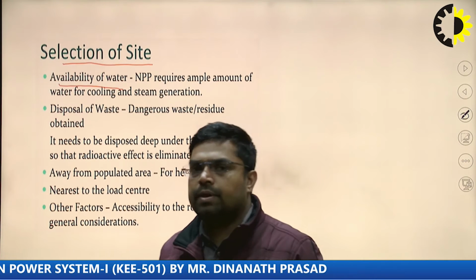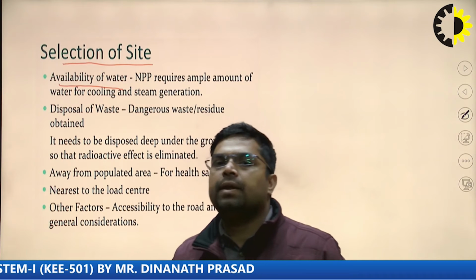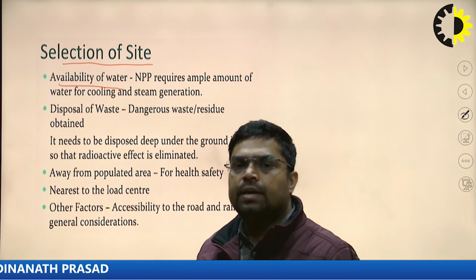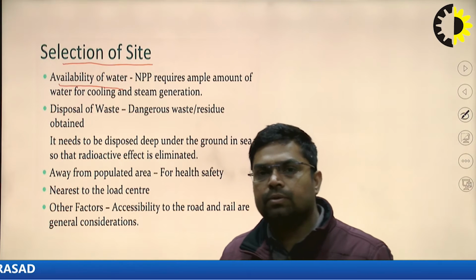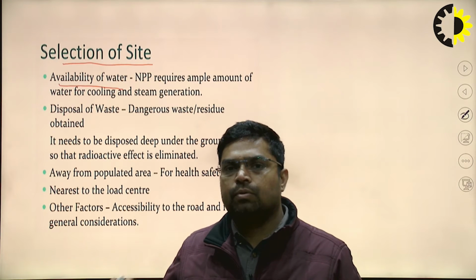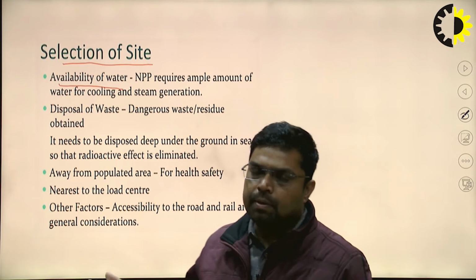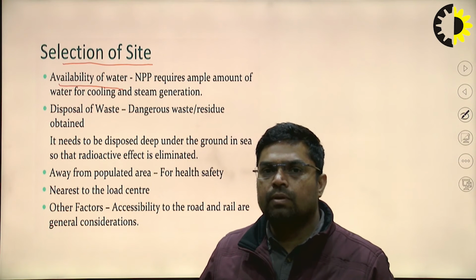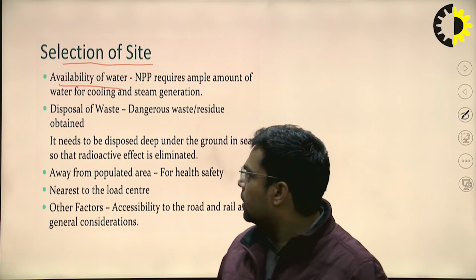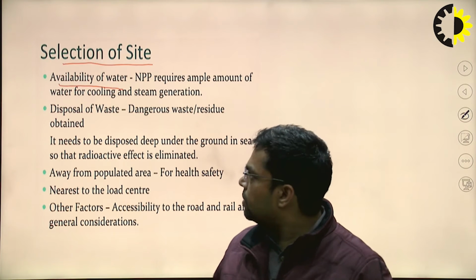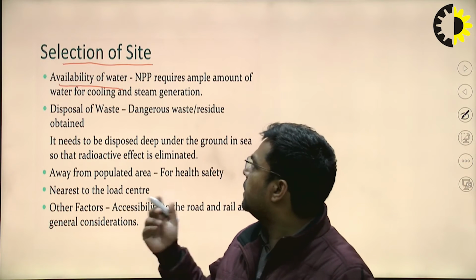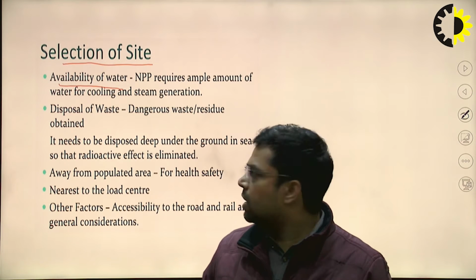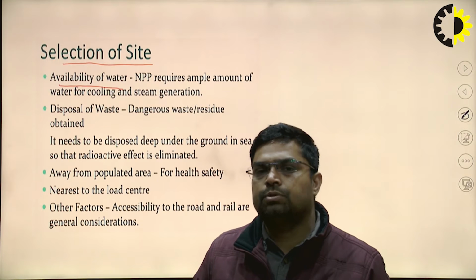What amount of water is required? If we compare with other power plants, like a coal power plant, the water requirement is very high in the case of a nuclear power plant. Although a coal-based plant requires a large amount of fuel, water is needed to cool down and condense the steam, and that requirement is very high in a nuclear power plant. That's why for any nuclear plant we choose, the water availability should be very high.